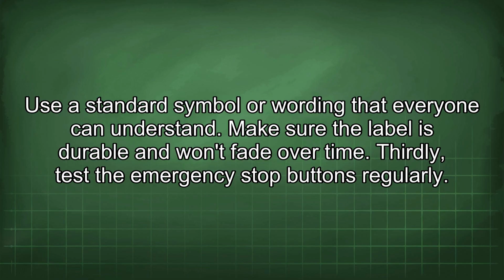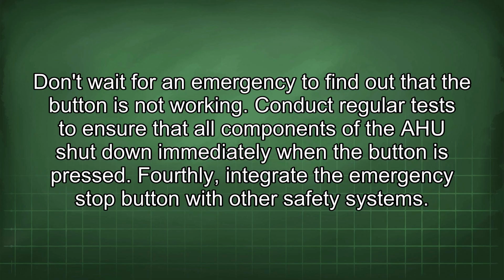Thirdly, test the emergency stop buttons regularly. Don't wait for an emergency to find out that the button is not working. Conduct regular tests to ensure that all components of the AHU shut down immediately when the button is pressed.